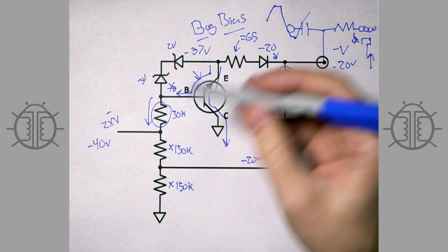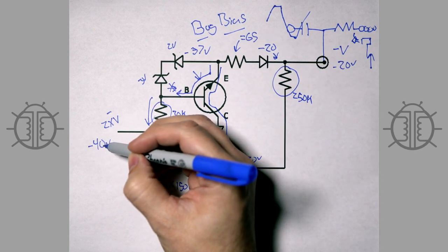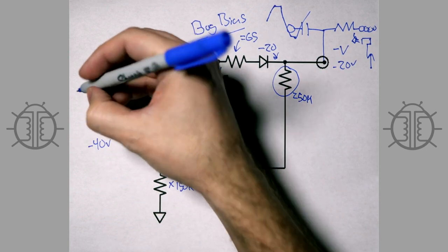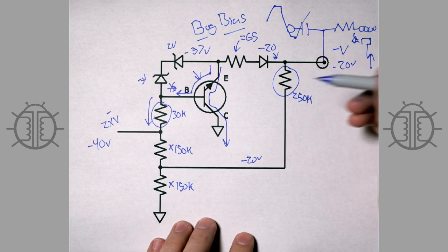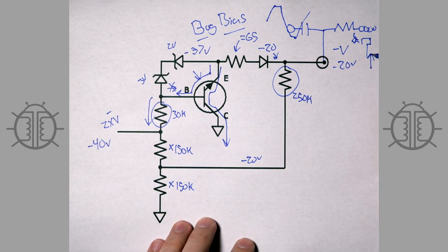And so you can see now, it doesn't matter where we place our negative voltage over here, it's always going to clip at 0 and twice the negative voltage. And that's how the circuit works. And that's all there really is to it.